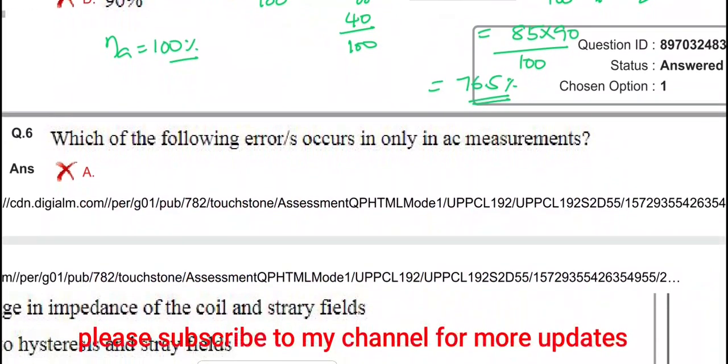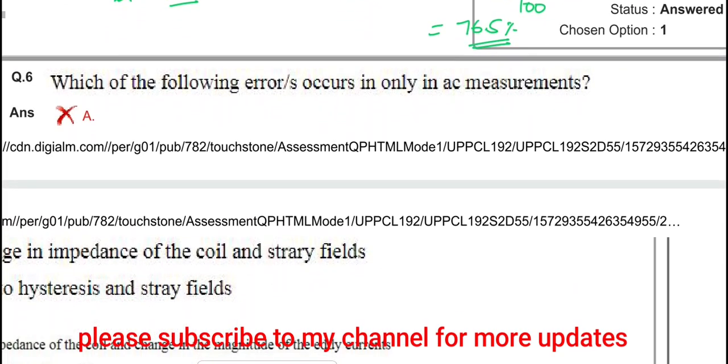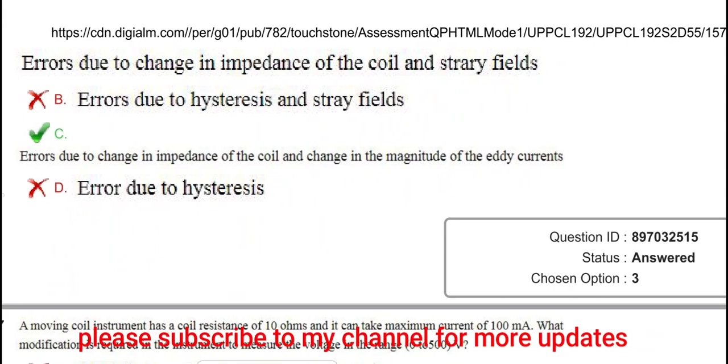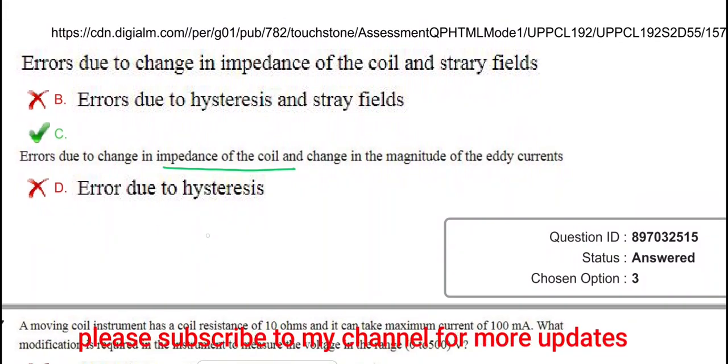Next, which of the following errors occur only in AC instruments? So what are the errors that occur? That is errors due to change in impedance of the coil. So change in impedance is due to change in frequency. XL is nothing but 2 pi f into L. So when the frequency changes, the inductance value automatically changes, and there is a change in the magnitude of the eddy currents.